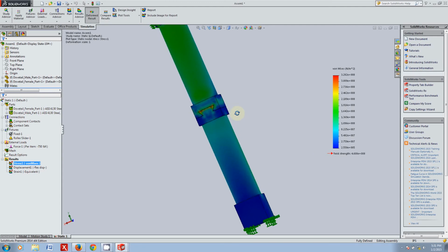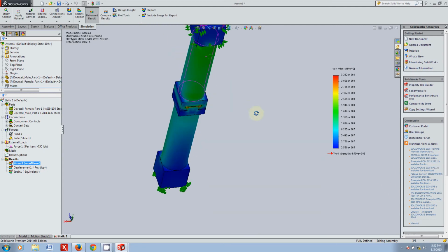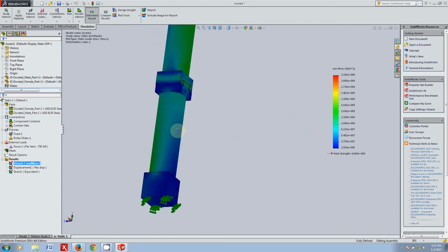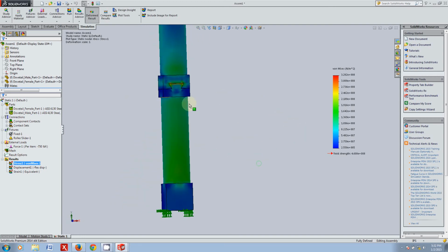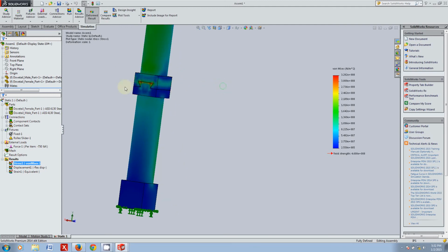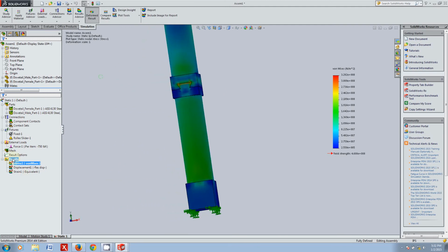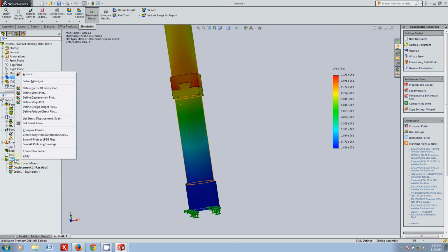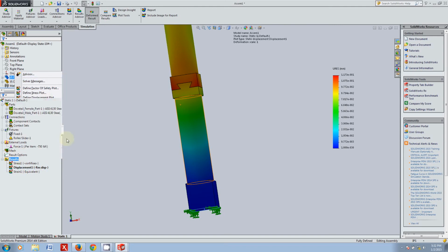And don't worry too much about the tubes, how much stress the tubes are experiencing, although I suppose in certain circumstances you might want to pay attention to that. But what we're really curious about is the stress distribution inside of our part. So it'll have results for stresses, displacements, and strains. Now, for purposes of demonstration, I'll just look briefly at displacements. Now, interestingly, you can check out displacements in a slightly different way. So I'm going to go and check out a displacement plot.